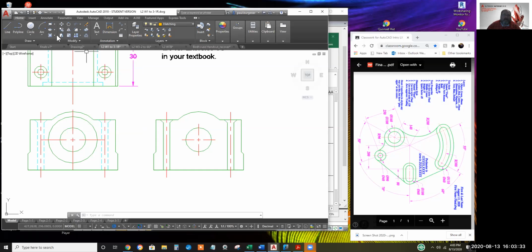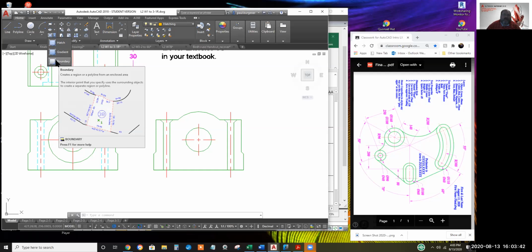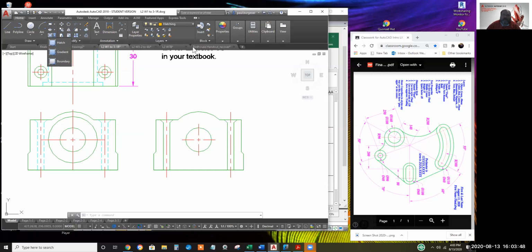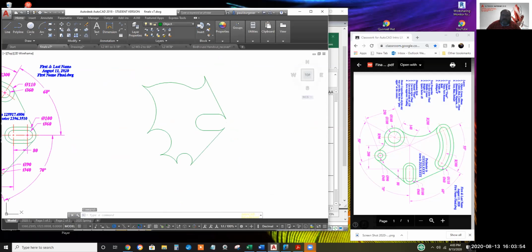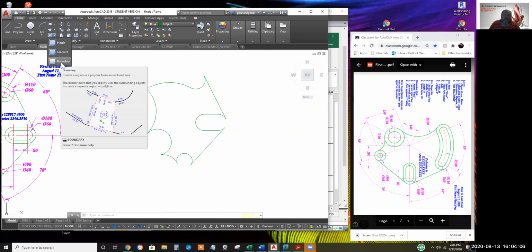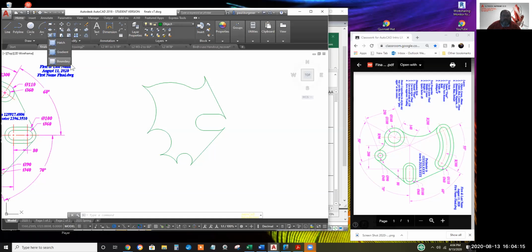Let me get a little off on a tangent, for which I may get criticized, but that's okay. Boundary is, how to put this, it's possible. Let's go back to our final project. You might be able to generate the polyline here by simply cross-hatching the shape to form a boundary. Maybe I should show that in introductory instead of the p-edit method. I have used it before.